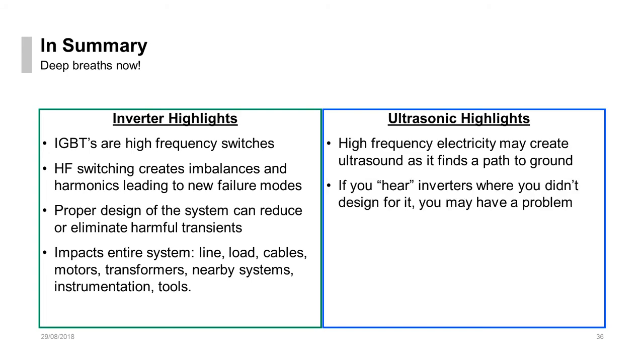So from an ultrasound perspective, this high frequency electricity can create ultrasound as it's trying to find a path to ground through ionization of gases. So if you can hear an inverter where you didn't design for it, you might have a problem.